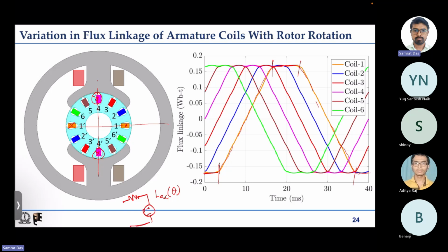And we can understand that in the transient case, any coil has some inductance, so there will be some inductance also. If you have taken the drives course, you know that the armature winding is also modeled with a constant inductance. So the question that we asked is, we understand the individual armature coils have an inductance that varies with rotor position, and the induced EMF is not constant, it is a quasi square wave in nature.